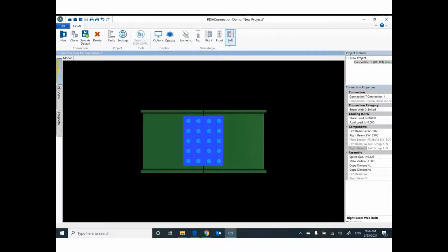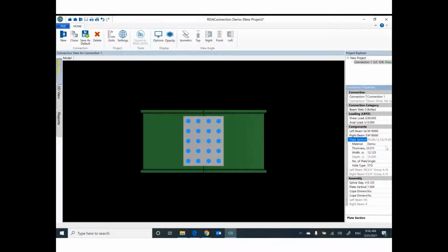If you would like to transfer shear without moment, you need to connect only web to web. So we have shear only. You need to define how much shear you have from structure analysis, how much shear at this point. Then you can try how many bolts for the blade section. I think we have an option here for blade section.